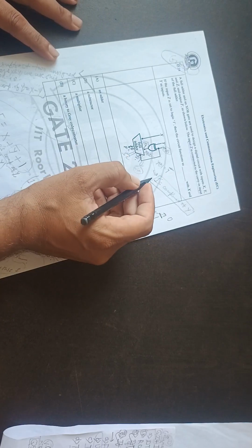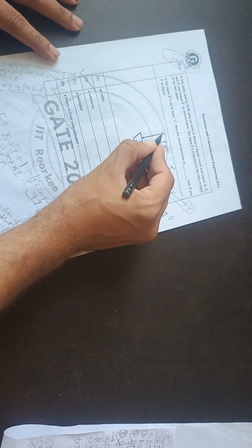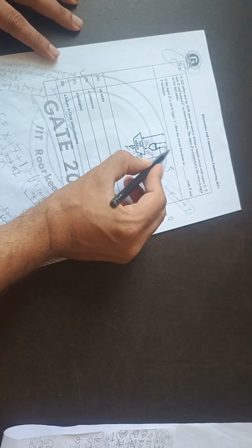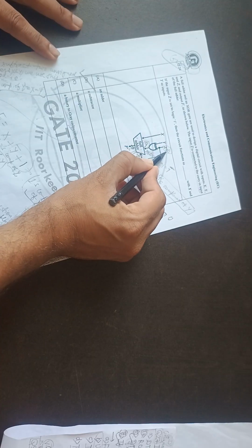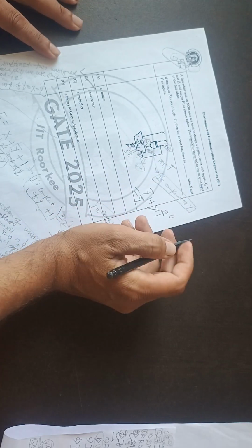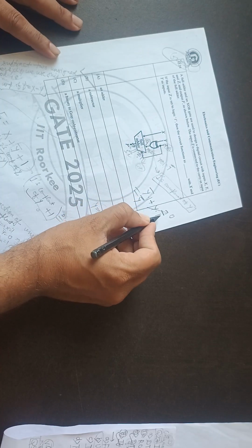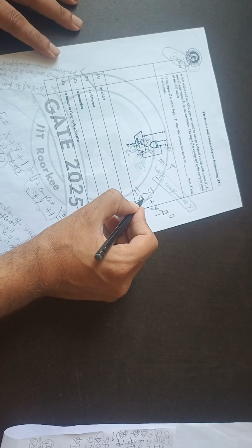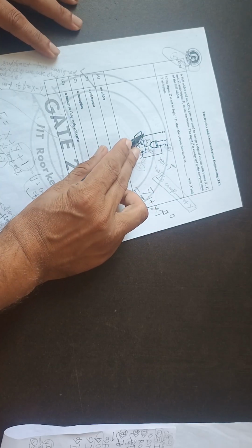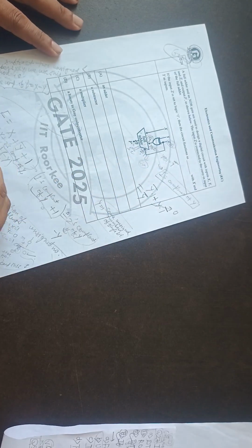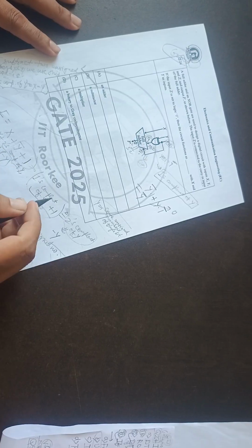So basically you can see that the output F is equal to X plus Y XOR 1. Y XOR 1 is Y bar, because Y XOR 1 is equal to Y bar 1 plus Y 1 bar. So this part is 0, and this is Y bar. So this part is Y bar, this part is X, and this part is 1. So F is X plus Y bar plus 1.